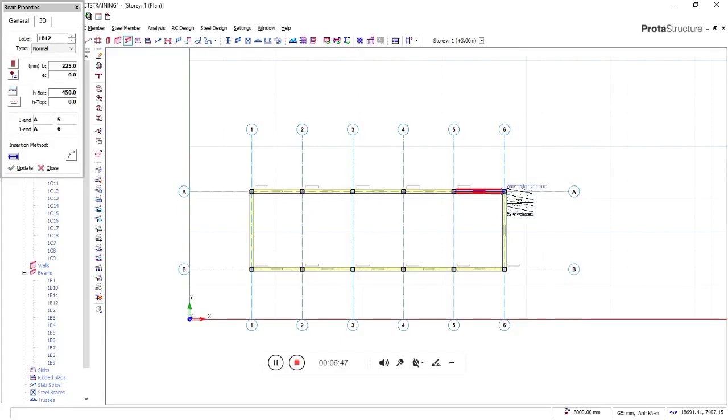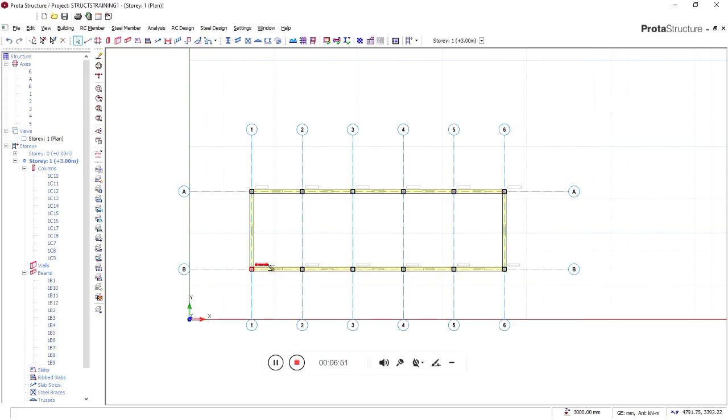You can see that there are two methods we have used now to add the beam. The first one, we click from one point to there, clicking one point to there, clicking one point to there. The second one, since we know we are going to have a continuous beam along this grid, I clicked at that initial point, and then I took it down. I didn't even click on all the points. I went to click on the last point, and it came up.